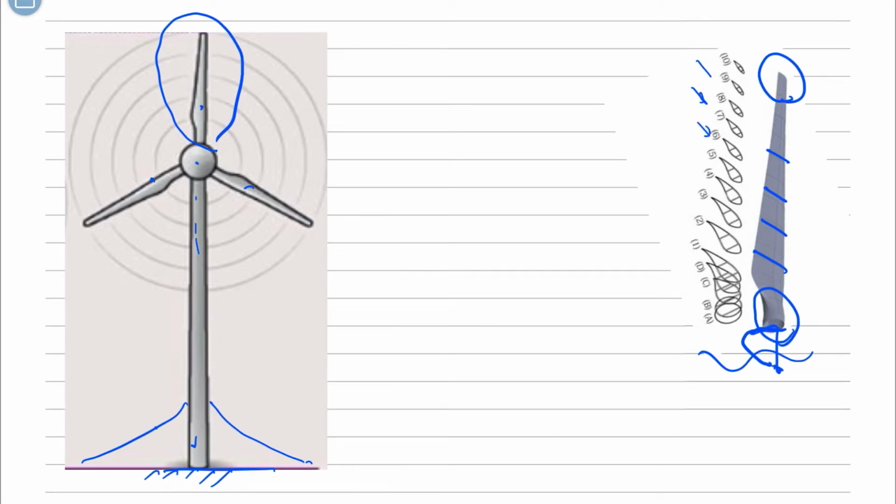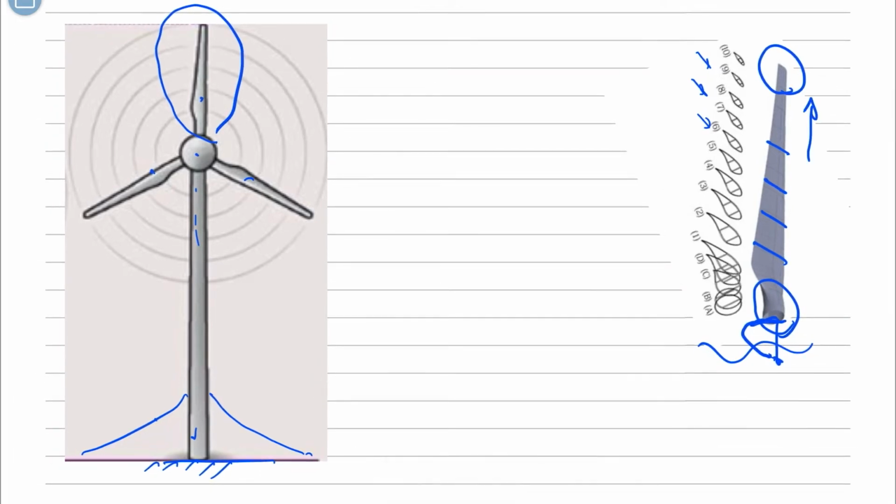If I take a look at one blade here, you see the blade looks like this. And if I again take a cross section along the blade from the rotor side, because here we have a rotor, towards the tip area, we get different shapes and sizes of the airfoil here. But there is another kind of distinguished characteristic here. The blade is also twisted towards the tip area.